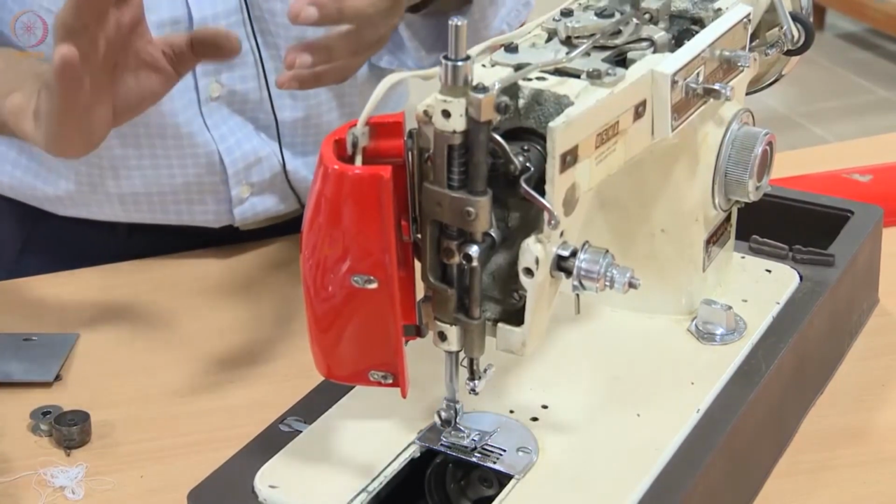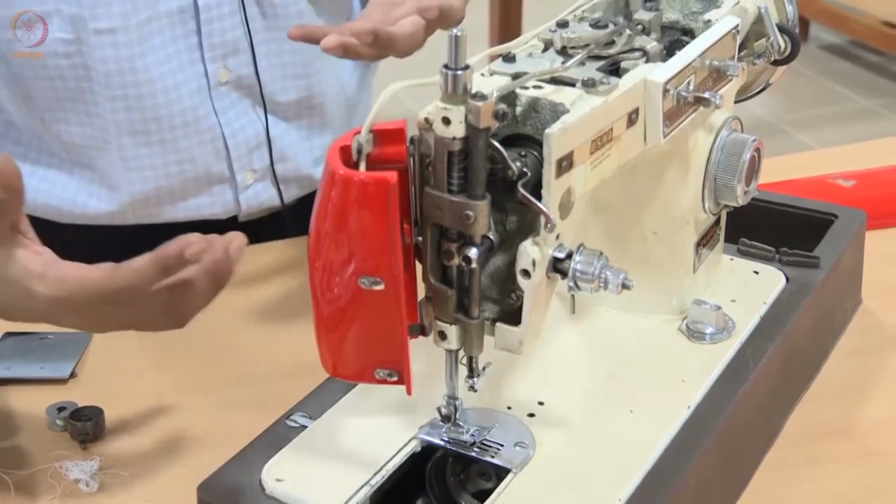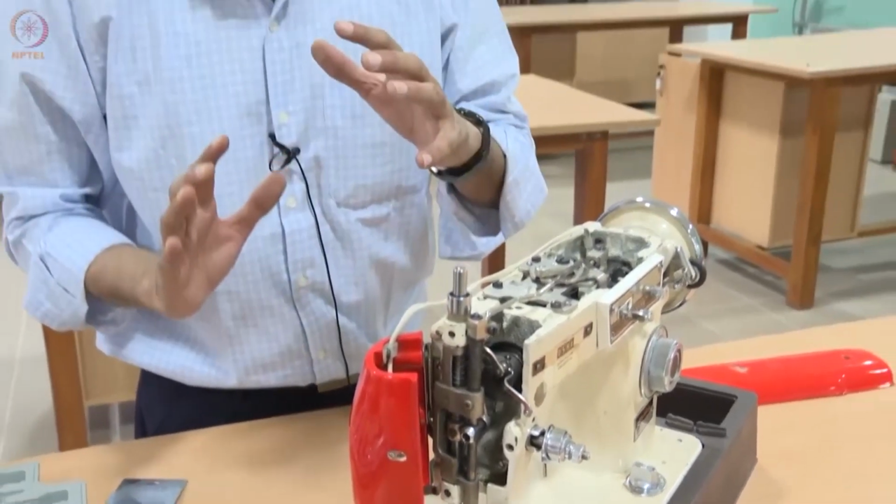Typically in an internal combustion engine, how we overcome this is, we have a flywheel that has a certain amount of inertia that helps keep the crank running in a certain direction, such that when you go through singularity, the momentum, the inertia of the system, takes it through the singularity. So keep this in mind, please. Whenever you have the crank part of a 4-bar mechanism as the input, you have to have some sort of a massive flywheel that gives a lot of inertia to the system. The momentum of the system as it is running takes it through the toggle point, since even when it is aligned, I would otherwise need another source of torque to make it pass through the singularity point. So please keep that in mind.